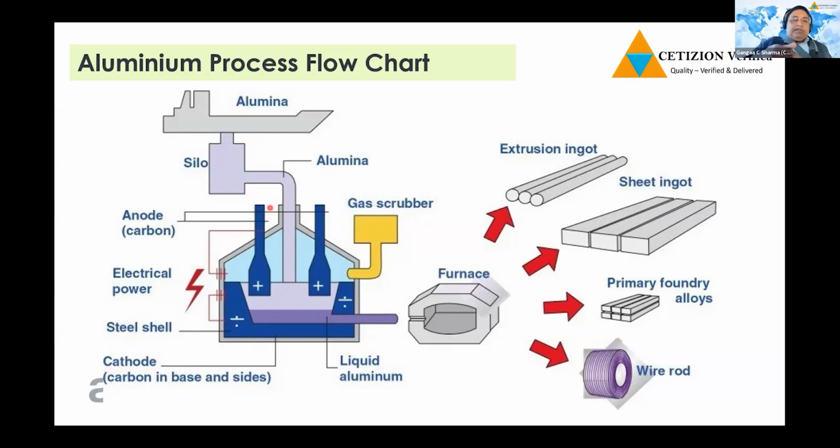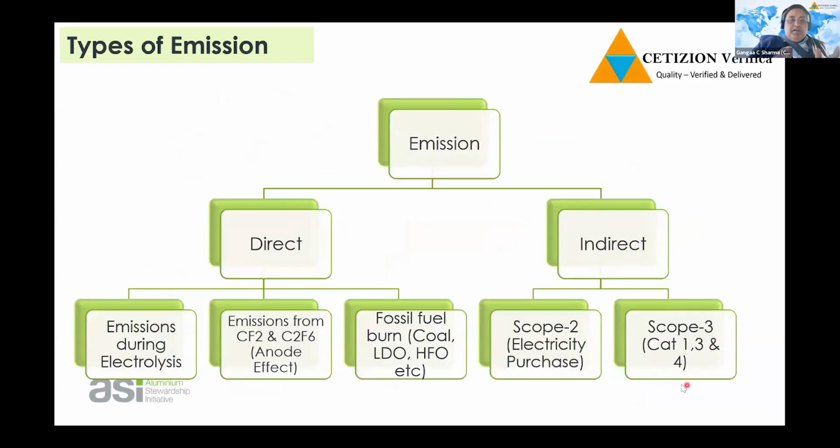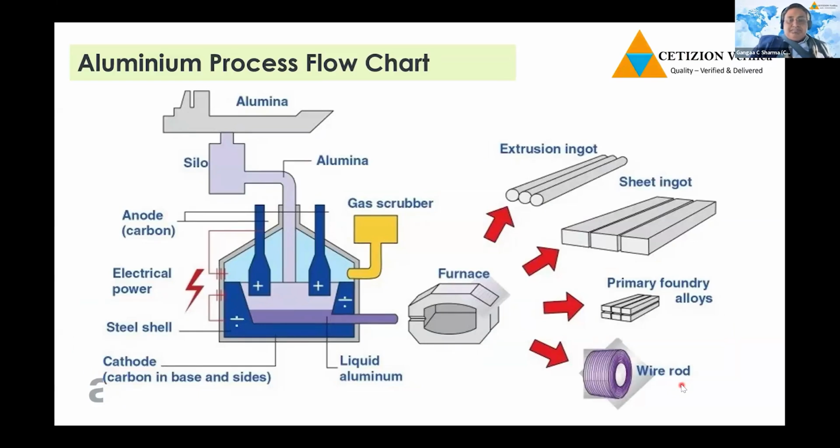And then you might have seen, for people from the smelter, there is a gas recovery system in which aluminium fluoride comes back for process efficiency. And finally, the molten metal, which is tapped from the pot, is further taken to the cast house, and it's created a bath. The slag, we call it the skimming of the dross, is taken away, the composition is made as per the aluminium grade, and finally transformed into the different products.